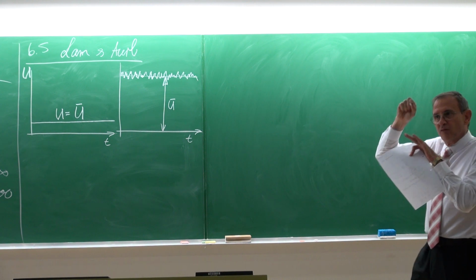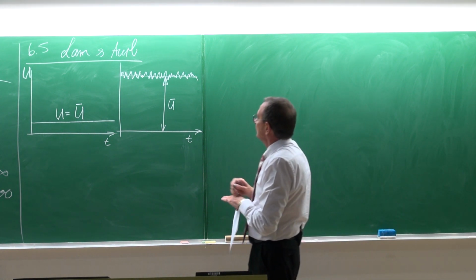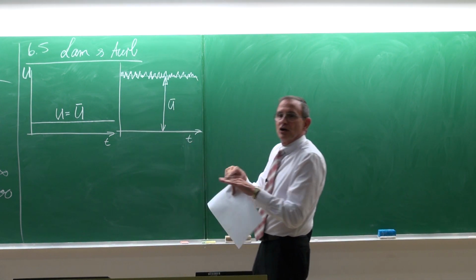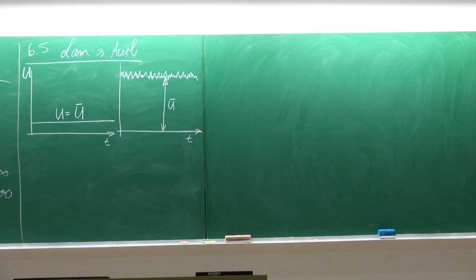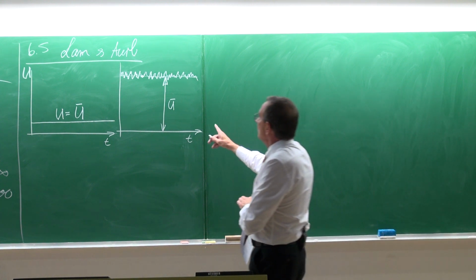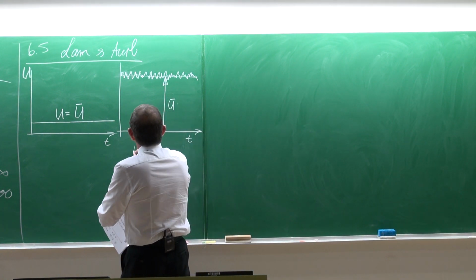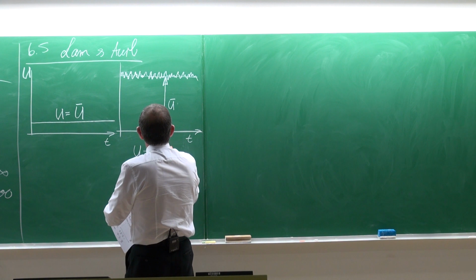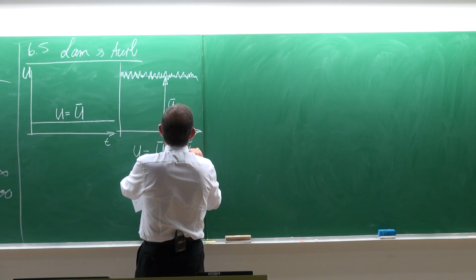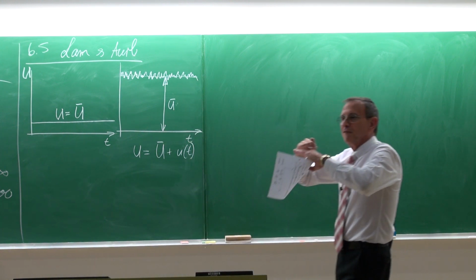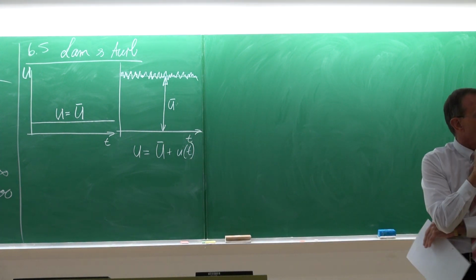So the measurements will all vary as a function of time, but if you take the average over 2 seconds, 3 seconds, 5 seconds, you'll get the same value. So that is turbulent flow. And for turbulent flow, the velocity is then equal to this average value plus a fluctuation component, how much it fluctuates around the average.